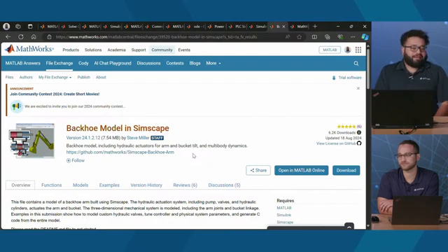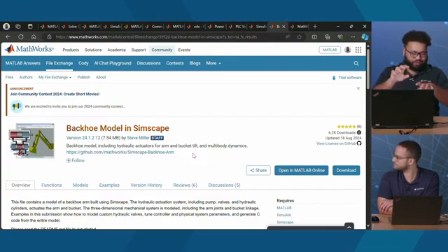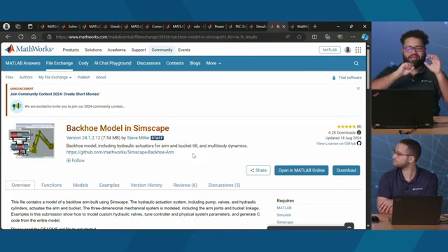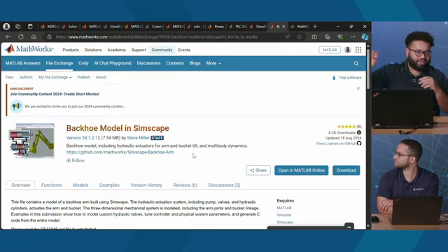And I think, Eric, you showed the block finder view in Simulink. When I first started using Simulink, I always preferred going to the library browser. If you look at the tool strip in Simulink, you'll see something called the library browser. You click on that. It breaks down the blocks for you, in terms of, the aerospace toolbox has so-and-so blocks.